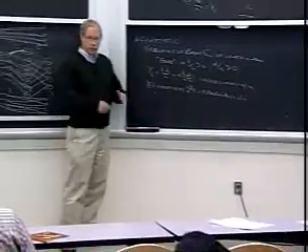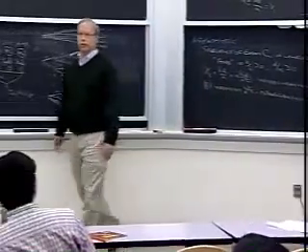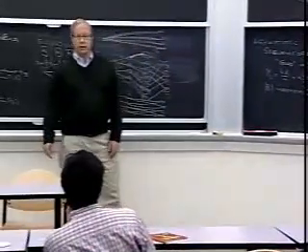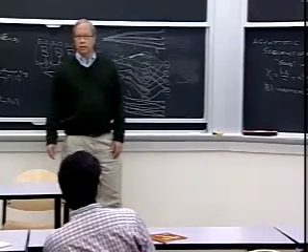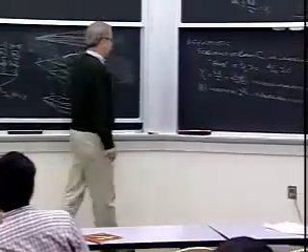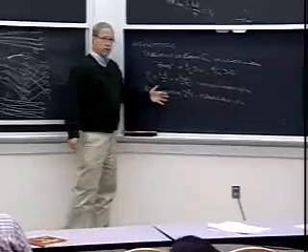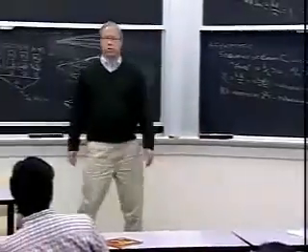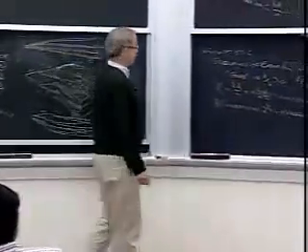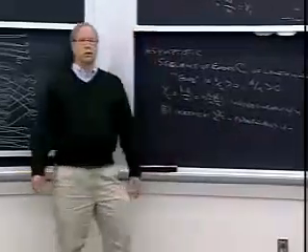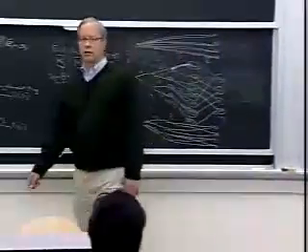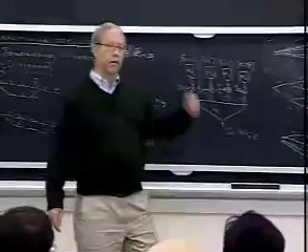The complexity of that, computing the distance to every code word, that certainly goes up exponentially with n, exhaustive decoding, comparing with every code word. But now we have a new method, which is, we hope, simpler, which is trellis decoding. But we find out, unfortunately, the complexity of trellis decoding is going to go up exponentially with n as well.